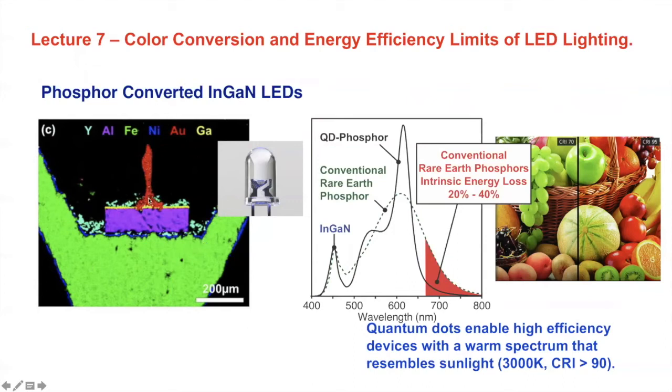This is one of the wires coming down, contacting this indium gallium nitride crystal, which is this thin yellow stripe here. Labeled in yellow is the gallium in this device. So you drive electrical current through this wire and into this crystal, and then out into this aluminum block. So you drive half an amp of current through this tiny little flake that's a quarter of a millimeter by a quarter of a millimeter square, and a couple of microns thick.